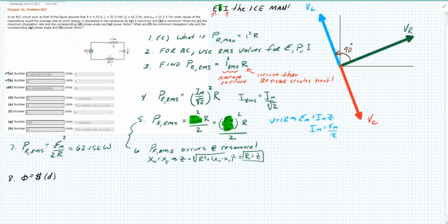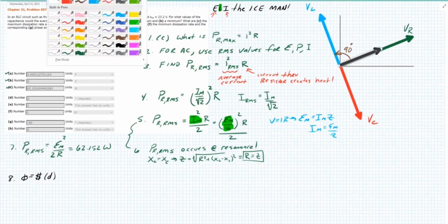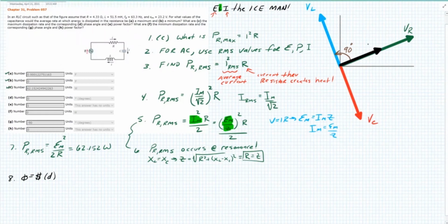And you might say, hey, Chris, you're drawing voltage leading voltage. And then I would respond by saying, you're right. Let me be more precise, because the circuit current is always synchronized with the resistor, because the resistor is just a dumb physical device. A resistor does not have any complex electromagnetic behavior like an inductor does or a capacitor does. So that's why this is current.